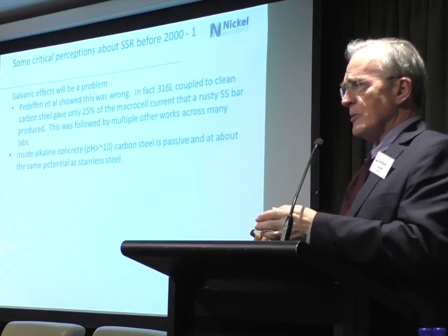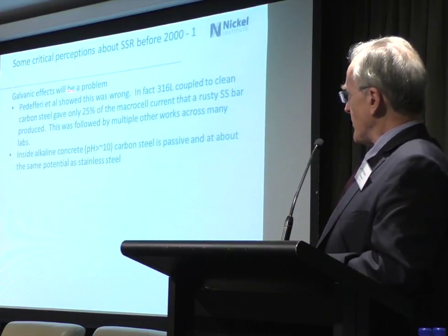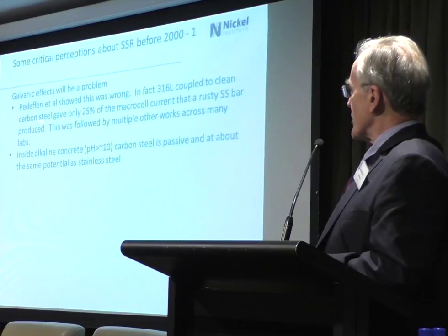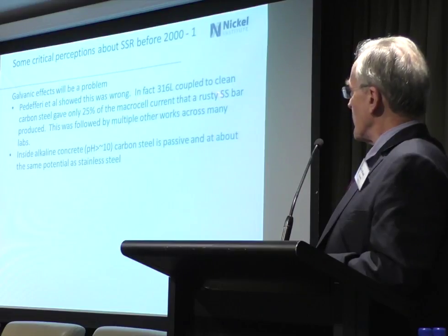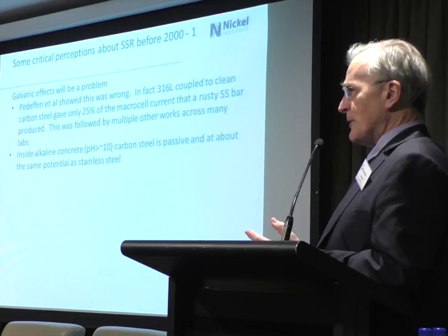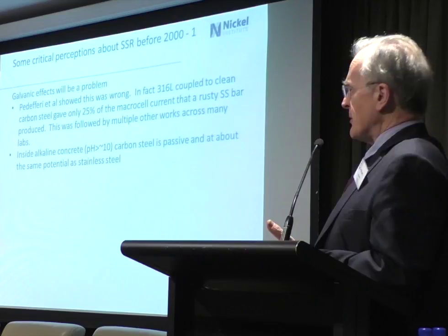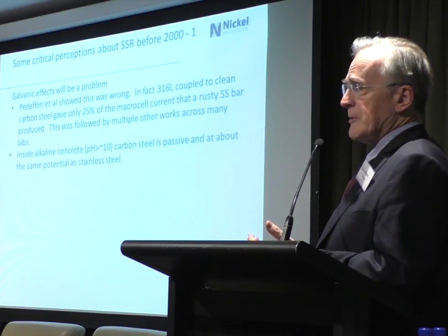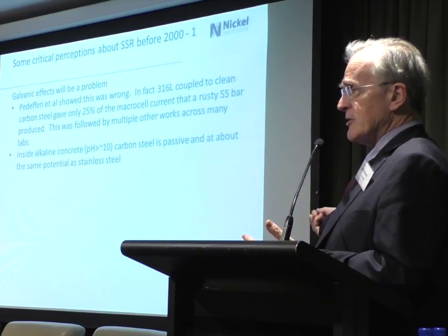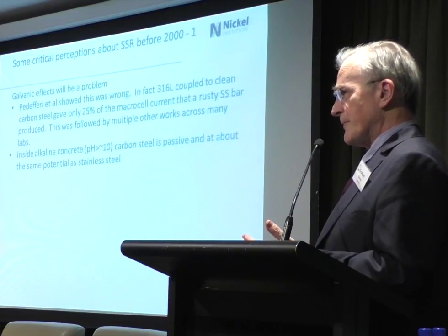And that's true. But putting it in concrete, enormous amount of work done by him and then lots of other people since, showing carbon steel, you only got about 25% of the macro cell current with stainless steel if you hooked it up to a good piece of carbon steel in concrete, in a simulated concrete, compared to what would happen if you had a piece of rusty carbon steel coupled to the same piece of ordinary carbon steel, which sort of knocks things on the head.